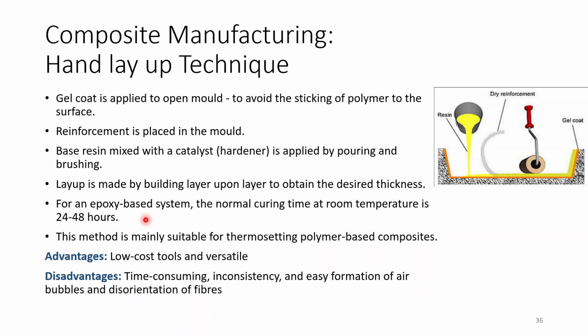For an epoxy based system, the normal curing time at room temperature is 24 to 48 hours, and this method is mainly suitable for thermosetting polymer based composites. Advantage of this method is that it has low cost tools that are used, and it is versatile. Disadvantage is that it is time consuming, inconsistent, and it is easy formation of air bubbles and disorientation of fibers is possible.